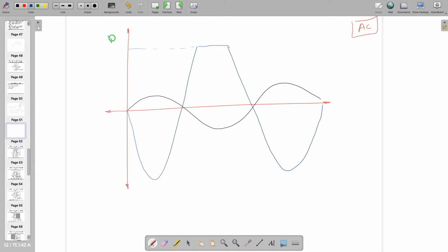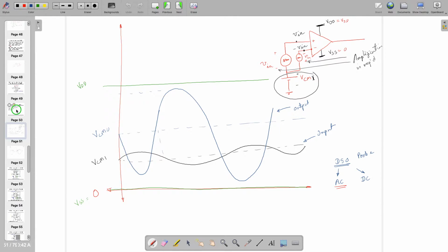So this is amplitude with respect to time. So it's getting saturated. So it's a bad design, right? But you forgot to see the DC setting. If you see the DC setting, then you will see that there is one extra component or the DC term which is going to be added over here, and that might be the reason to get the saturation.